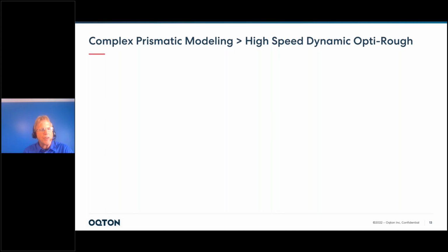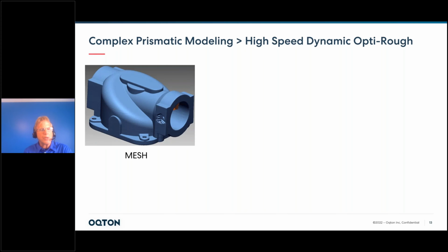So very, very clean transition going from just a very basic part scan going into the model and then building design intent and manufacturing intent into that model to make sure that the subsequent tool motion is what we want to see. Stepping into our second exercise, we're going to stick with a prismatic model for now, but two differences